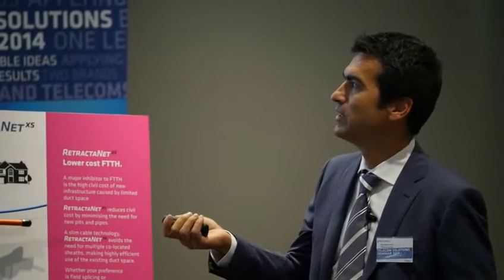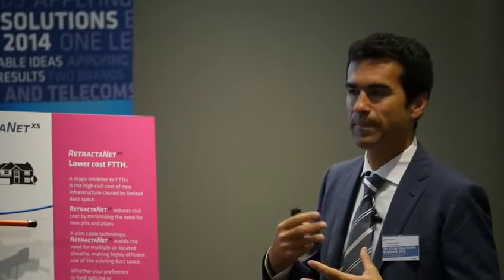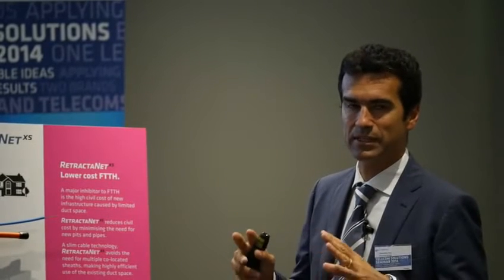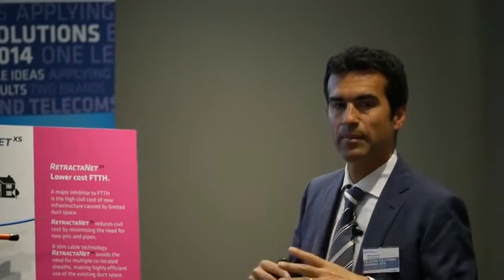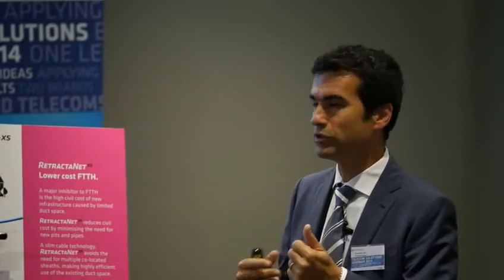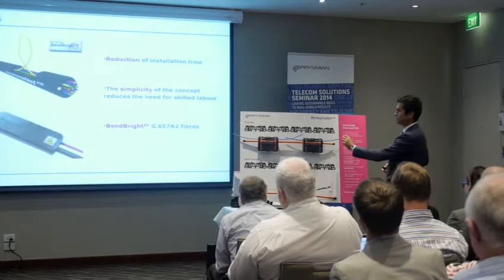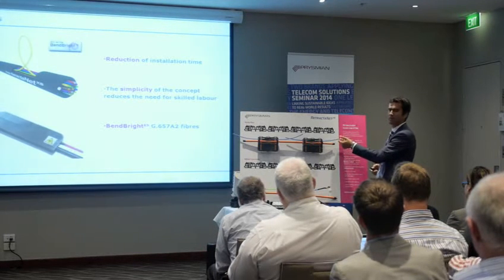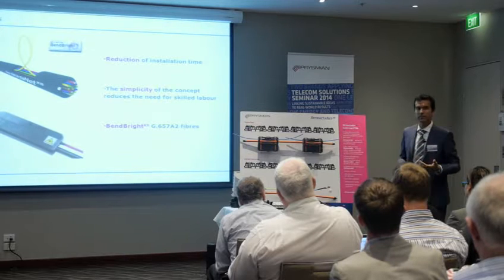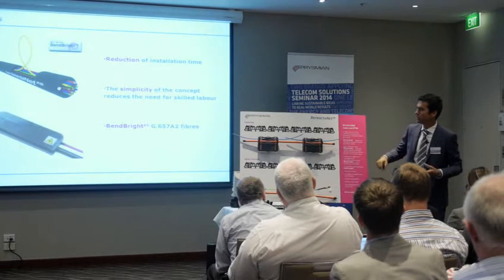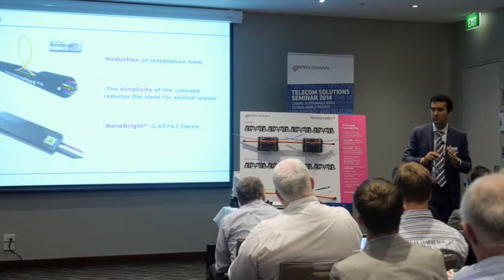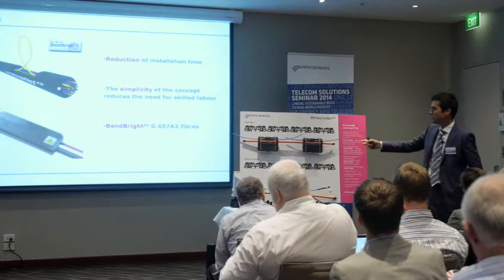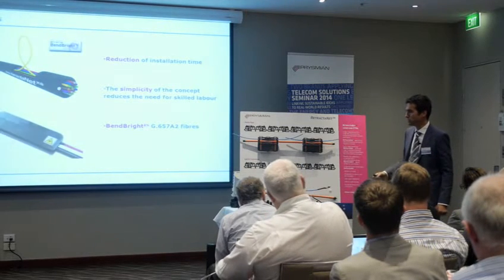Because the fiber, we saw this morning all the theory about the coating. The fiber today is still sensitive to water ingress and vapor, but the protection of the fiber itself through the coating, then through the insulation, the buffering that you have around, is enough that this kind of fiber could live, we made a lot of tests, could live in water as long as it's not damaged or broken. They can live more or less forever in water. So in the end of the day,